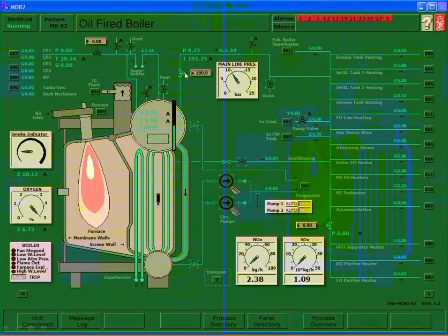The steam that's being created will push the air out the air cock, and once you see steam coming out, then you go ahead and close it. On shutdown, you would open that up to prevent the drum going into a vacuum when the steam collapses. The reason that you're worried about that, it's not going to hurt the boiler per se. I mean, this drum is typically meant for high pressure.